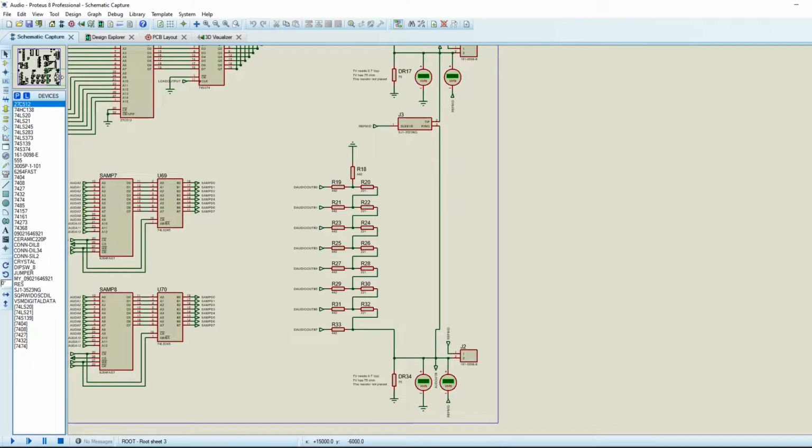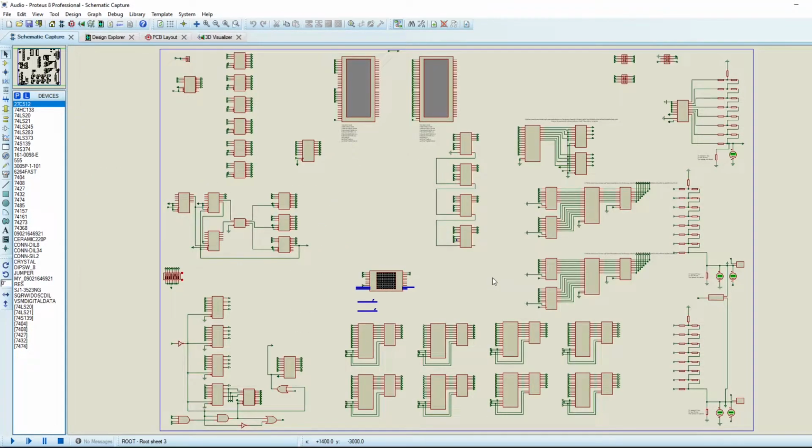And then the reference middle is output into these, I think they're RCA connectors, which actually I'm not using. What I am doing is that in the final PCB, I'm only using this microphone stereo socket here. Okay, and then all of that gets combined into there, and we can see here that we've got the reference mid voltage going in onto the sleeve, and then the tip and the ring are the 2 different stereo channels. Okay, so we have the other stereo channel. Okay, so that's pretty much all of the common logic from the PCB.